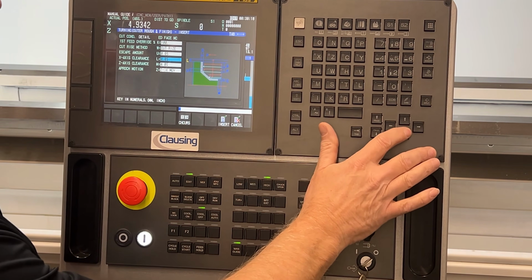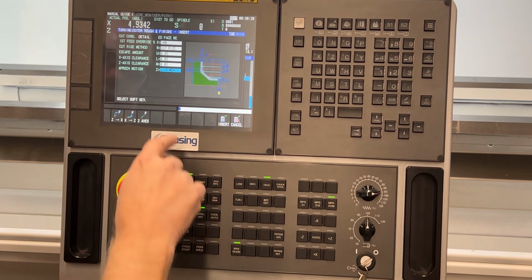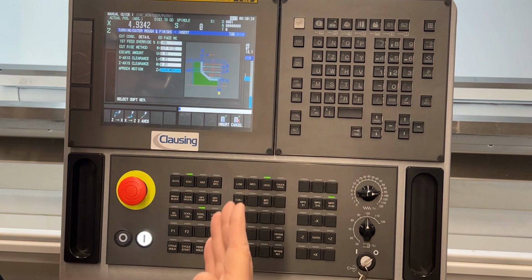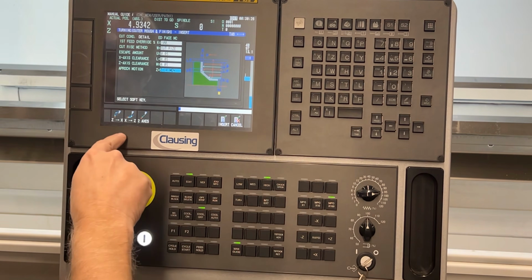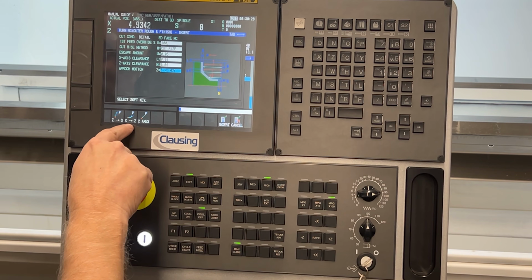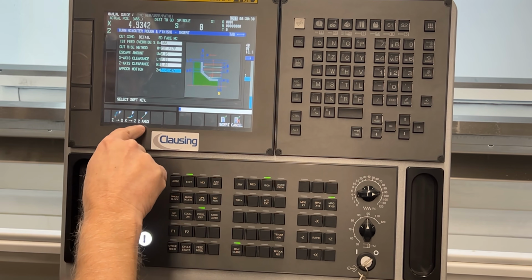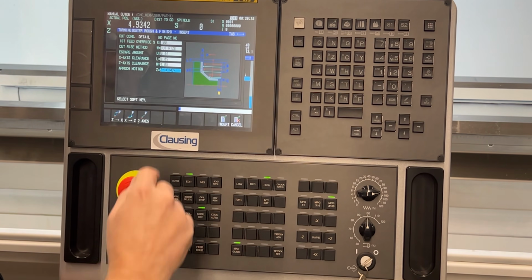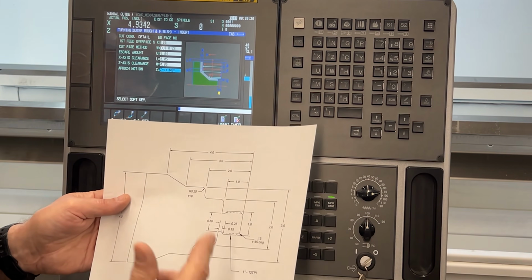How it gets there from that is also determined in here by, in this case, Z then X. So do Z first, then X. You can change that to go X first and then Z, or 2-axis move. And it still will use that clearance position so it doesn't go right to the corner of the part.